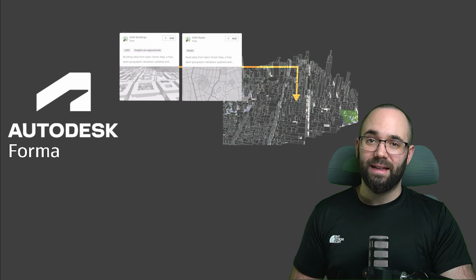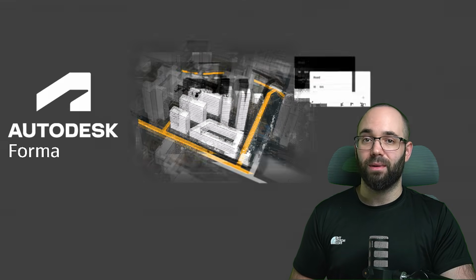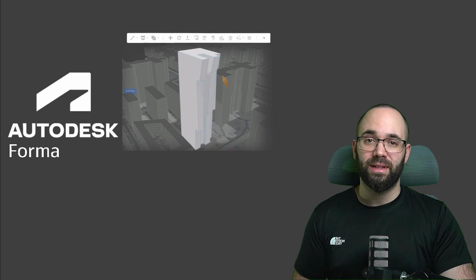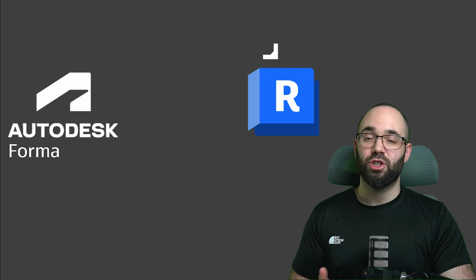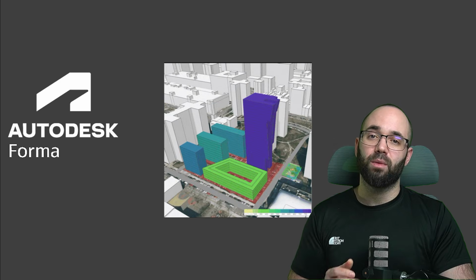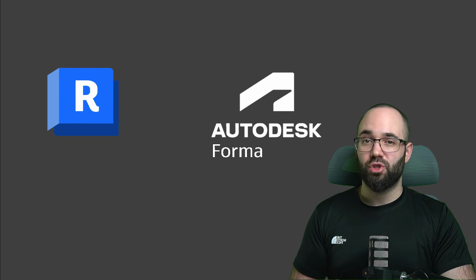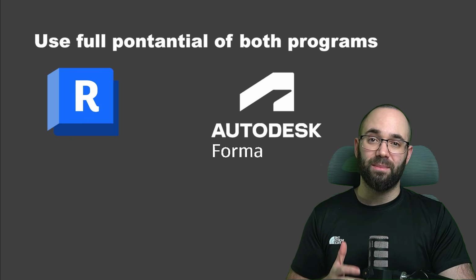For example, I would definitely get started in Forma to get my site data like the terrain, roads, buildings, and the aerial photos. This is also where I would create my initial designs, perhaps even implementing site automation. If I need more complex design, I would make it in Revit and then just load it back into Forma. The initial analysis before exporting I would run in Forma, and then I would export everything into Revit. In Revit, I would develop the design to an advanced stage and probably bring it back into Forma a few times to run analysis along the way before finishing the project in Revit. This way, we're getting the best of both worlds.